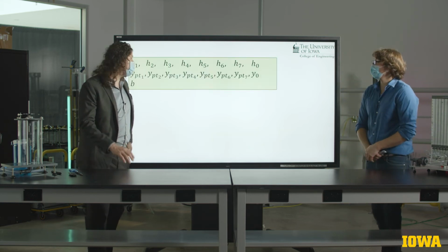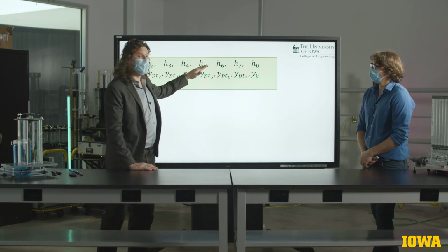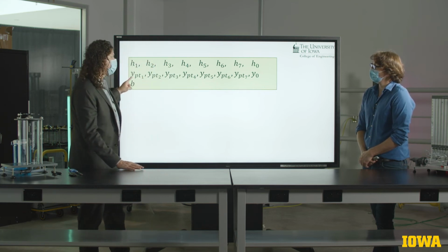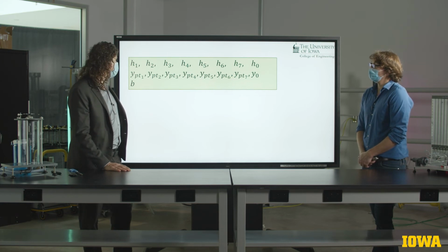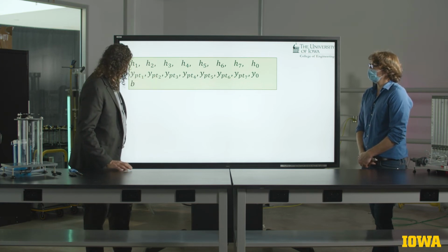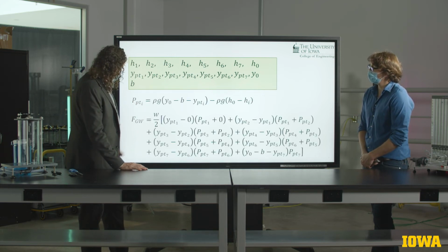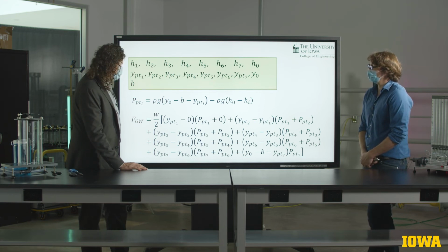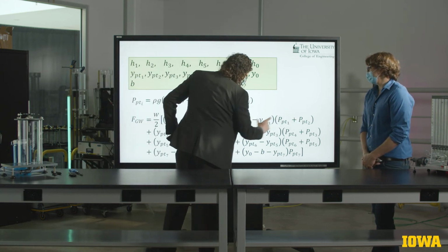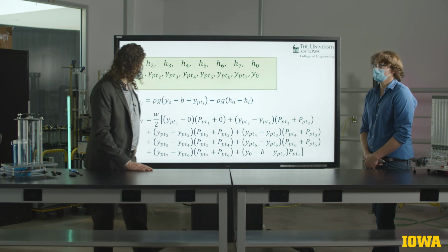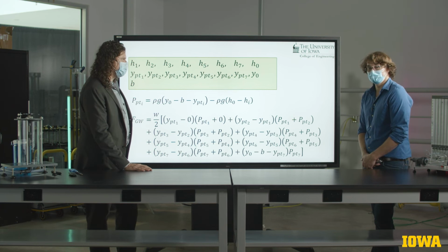Yeah. So in that method, we make measurements of the water elevation in our piezometers. And we also have measurements of the separation between the places in the gate where we made our measurements. So we combine those measurements in our data reduction equation, which was this kind of sausage-looking equation, but it's nothing but a sum of pressures multiplied by an area of the gate. Here, the width of the gate is another one of the measurements that we need.